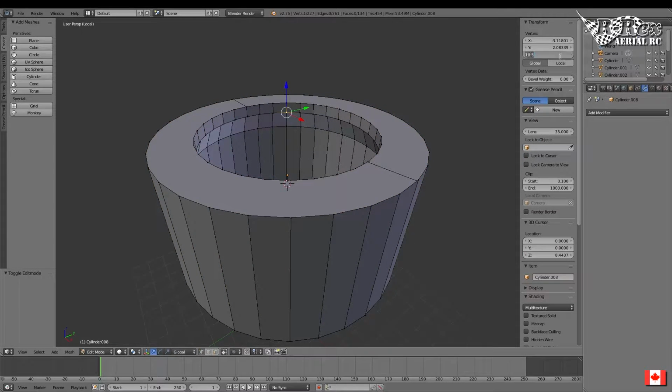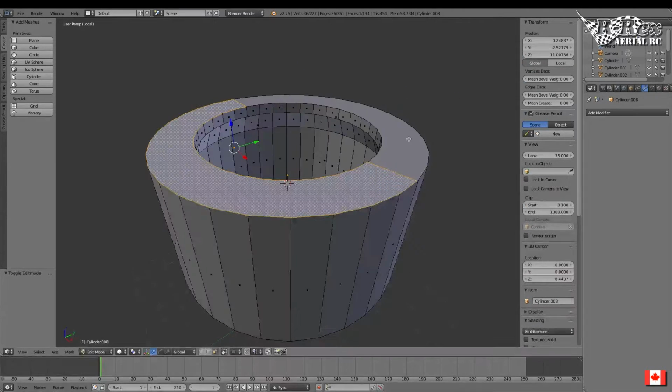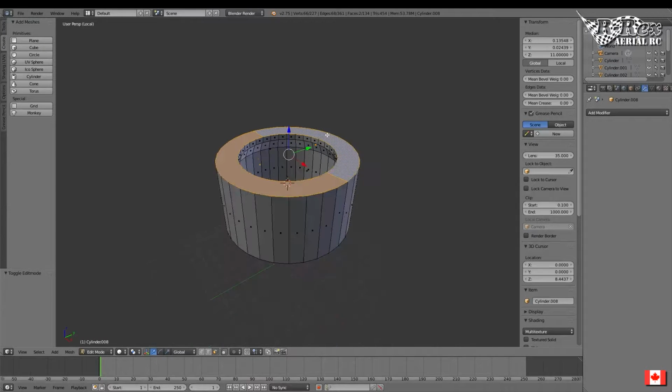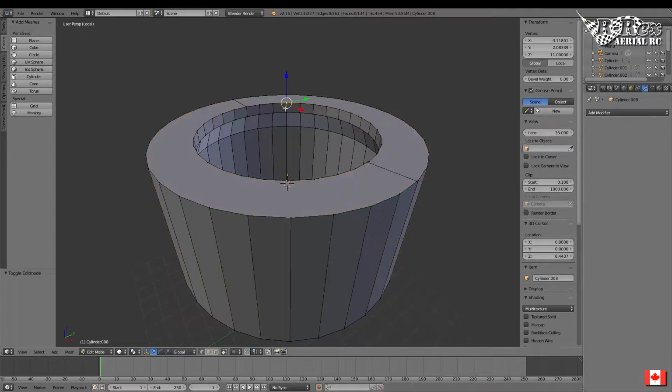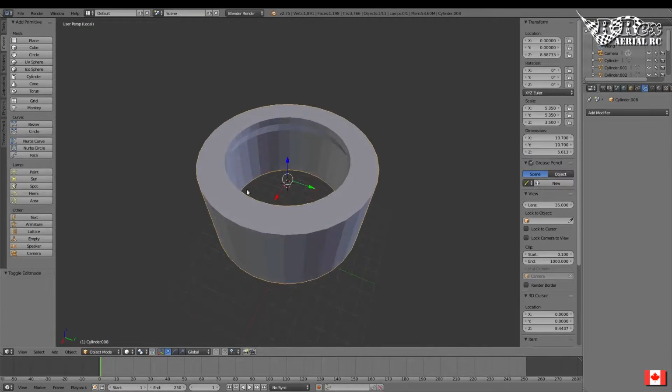So this is 10.5 is what our upper edge is. Let's say we want 0.5 millimeter on the upper face, so 10. Oops, escape. 10.5, we'll go 11. So that should be 0.5 all the way above. Perfect, so that's 0.5 millimeter thick.